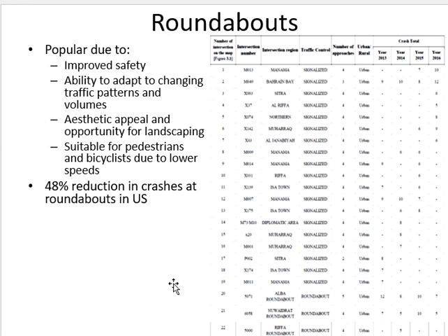Okay, roundabouts are becoming popular mainly because of safety, because for any other intersection, when you are entering the intersection, your angle is straight. Like you are going in right angles or straight. But on a roundabout, even when you enter, your angle is reduced. So if there's a conflict, it will not happen head on or at right angle.